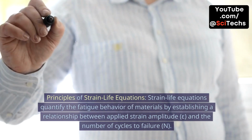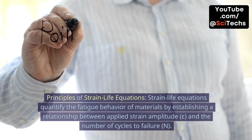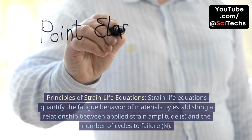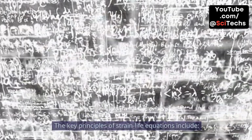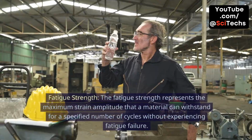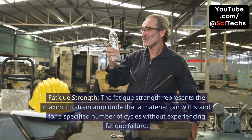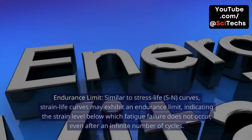Principles of strain life equations. Strain life equations quantify the fatigue behavior of materials by establishing a relationship between applied strain amplitude, epsilon, and the number of cycles to failure, N. The key principles of strain life equations include fatigue strength. The fatigue strength represents the maximum strain amplitude that a material can withstand for a specified number of cycles without experiencing fatigue failure. Endurance limit.